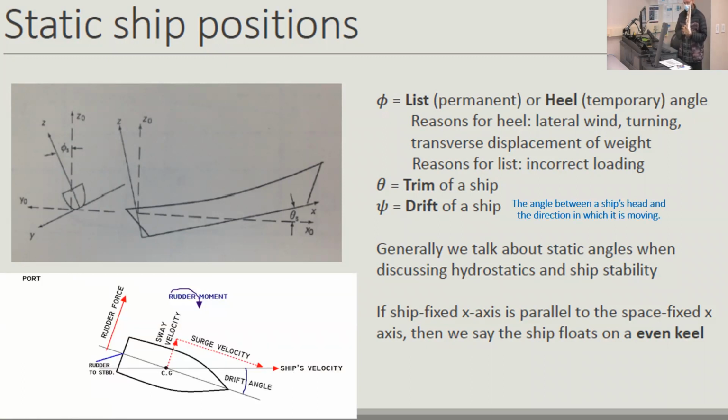Drift is, let's say your ship is angled, so it's going in. All right. So right now the ship is sailing towards you, okay? But something happens and the angle deflects slightly, but it still keeps going towards you, okay? Straight along the vector pointing along my finger. The angle in between is called the drift angle, phi, okay?